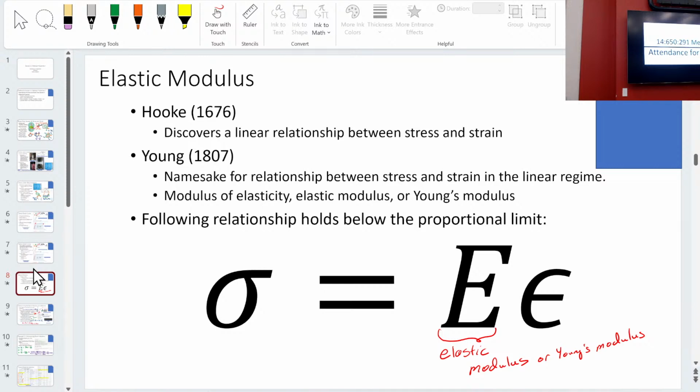First of all, tau means shear stress, which means we have a force acting along the surface. The first subscript is the face, the second subscript is the direction. So tau xy would be the x face in the y direction.